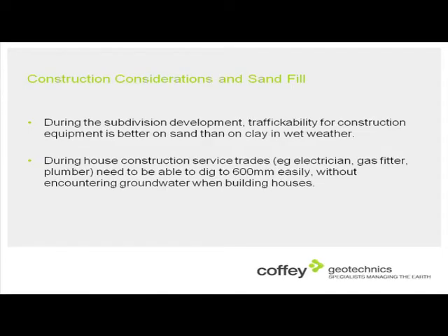And the house construction service trades in particular like the sand. They want to dig down about 600 millimetres for a lot of the services, and it's pretty easy to dig the sand and then put it back in the trench. It's a lot easier than working in clay.